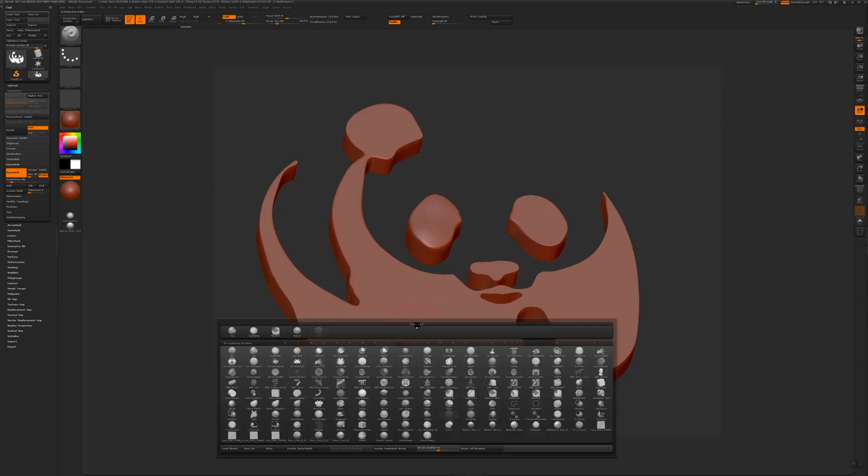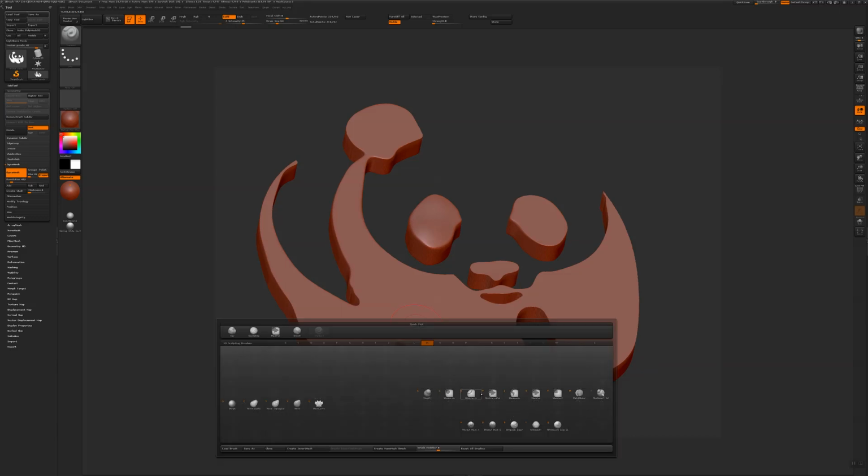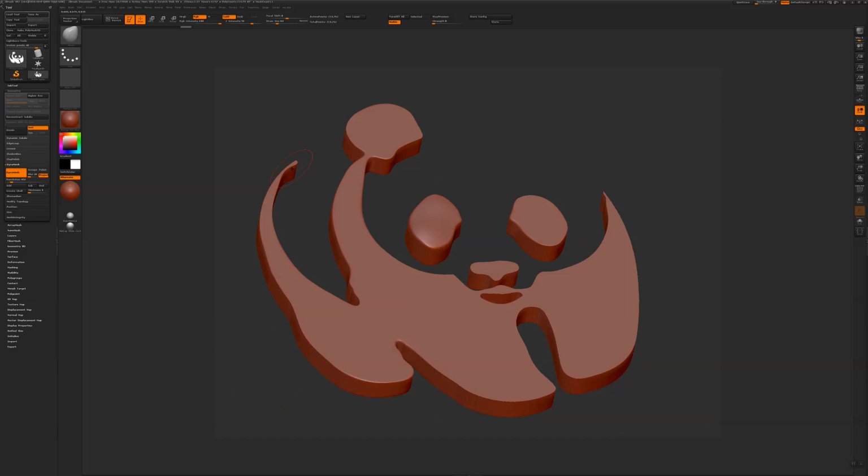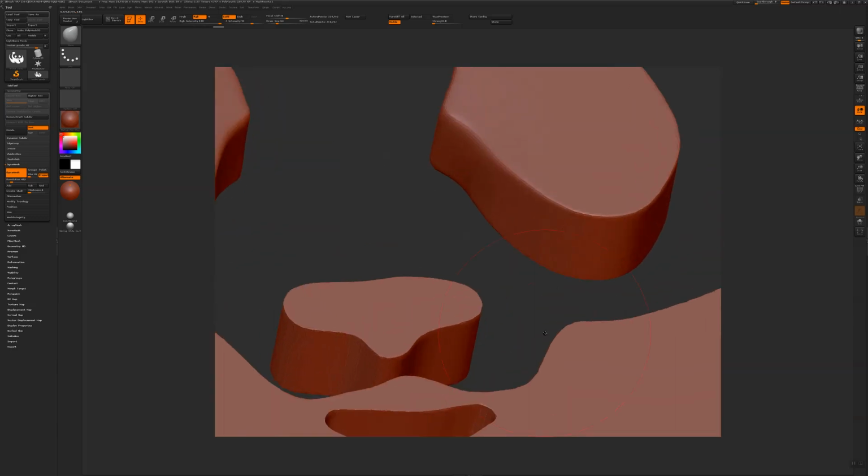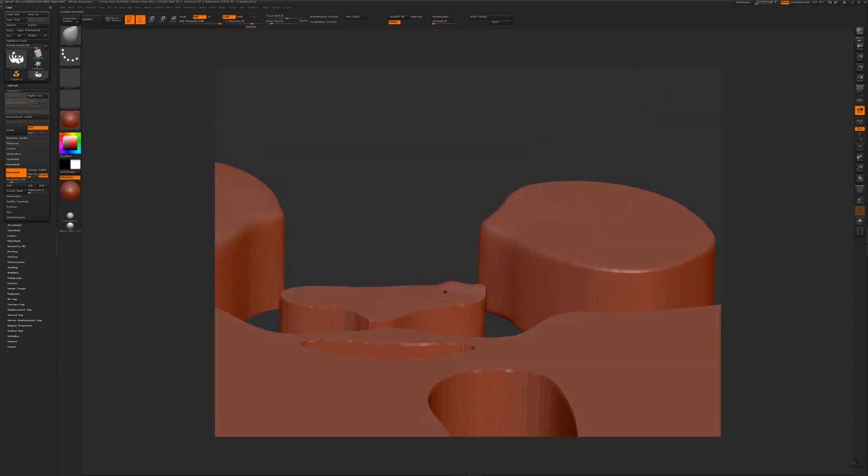Let me switch brushes. I'll go to the move brush. Where's the move brush? Move here, move brush. I can grab the end here and I can move it around. I can pull things here, zoom in, and I want to move this over here. Get really detailed. Make the brush smaller. I'm going to pull that here and start making little details that, if I was to try to do this in Rhino, it'd be almost impossible to do in Rhino, okay?